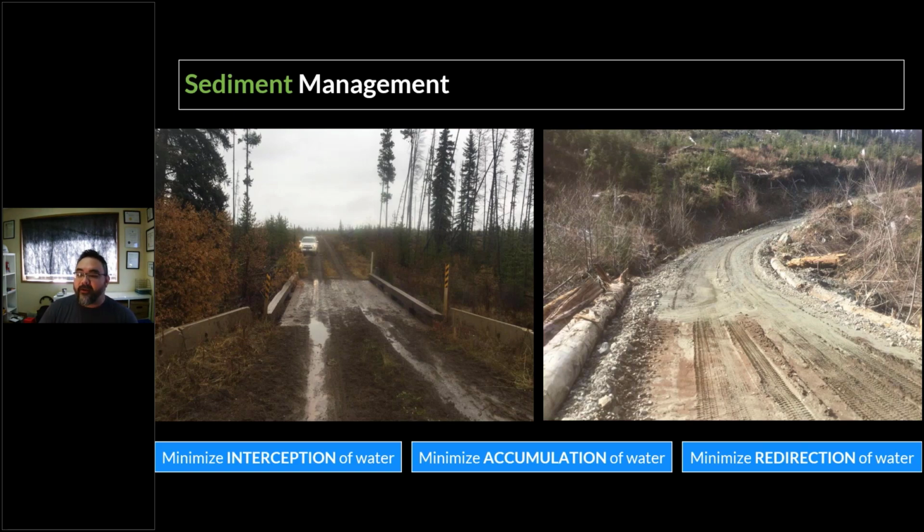If you're operating in the wet, or you're dragging more silty materials from the roads that are not surfaced further away on the approaches, or as in a lot of cases, you've got rutting. You can see that on the left-hand side there. It doesn't matter that you've done all those things, you're still going to have sediment coming down to your crossing, especially if you're in an area of predominantly fine-grained soils. And so you've got to think about that, especially if you're in a watershed that's sensitive to sediment, or you've got a water intake or fish right there.